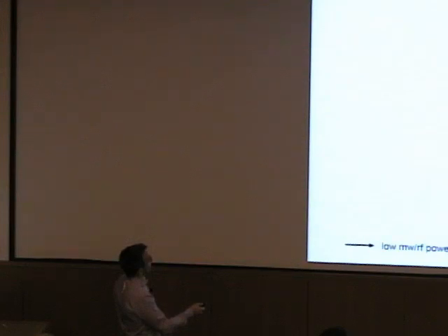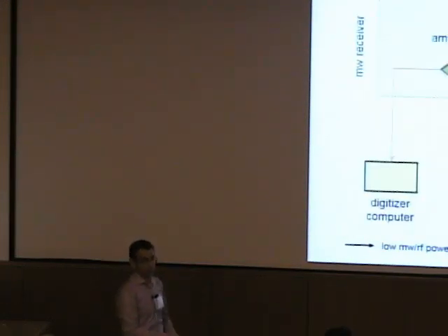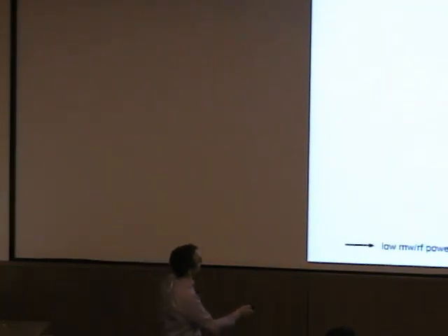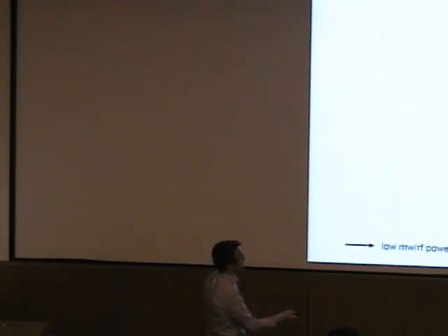Then this is all low power. Then it goes to a high power amplifier, which is always very expensive. And then the red arrow indicates now we have high power pulsed microwaves. They go to the resonator in the magnetic field of the EPR spectrometer and excite the spins.